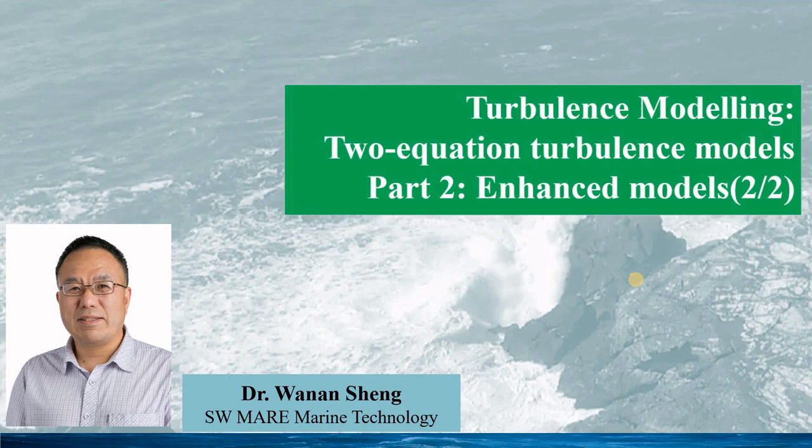Hello, welcome to my talk on Enhanced Turbulence Models, Part 2. In this talk, we will introduce the popular and useful two-equation turbulence models, both in practical applications and in the research community, including Menter's SST model and the Algebraic Reynolds stress model enhanced two-equation turbulence models.